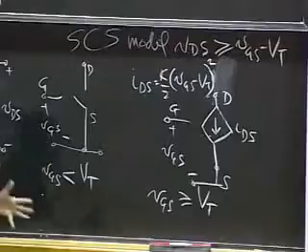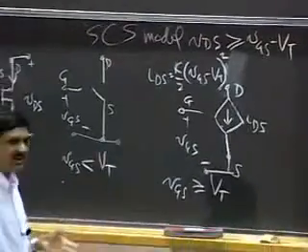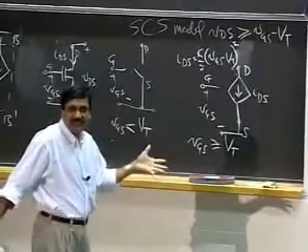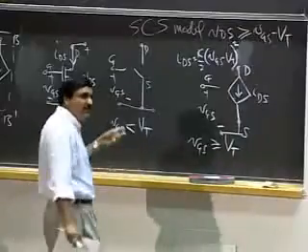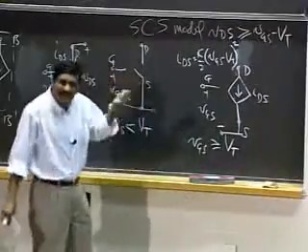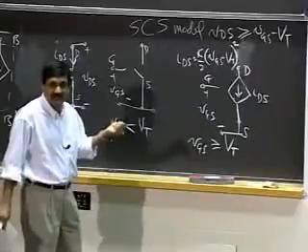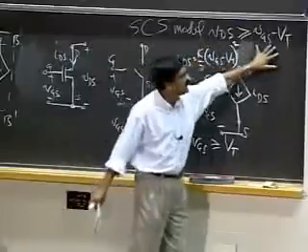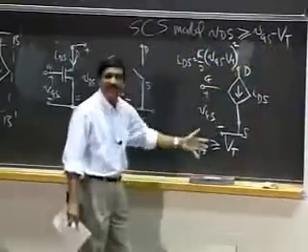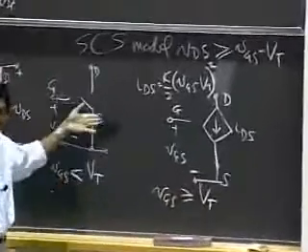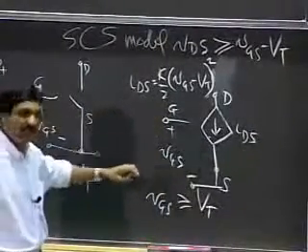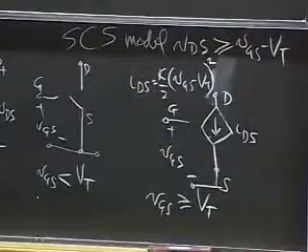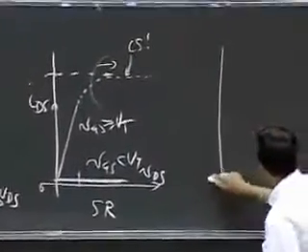And again, remember, this is not meant to be conflicting. It's not like, gee, how can the MOSFET look like a resistor and then suddenly become a current source? Well, the two regions are different. It's not that it's behaving as a resistor or as a current source for the same parameters. No. When VDS is less than this right-hand side, it does behave resistively. Okay, the SR model applies. When I increase VDS beyond a point, the current saturates and the SCS model applies, like so. Okay, so let's draw.